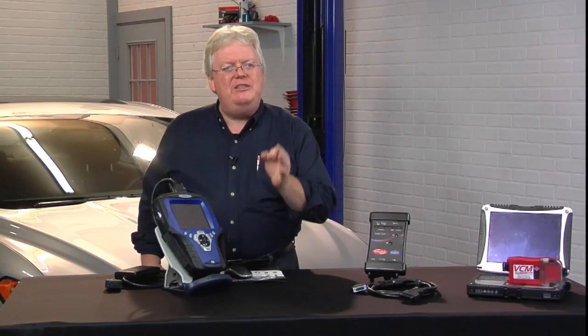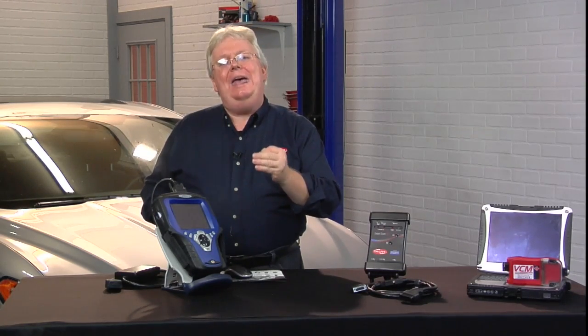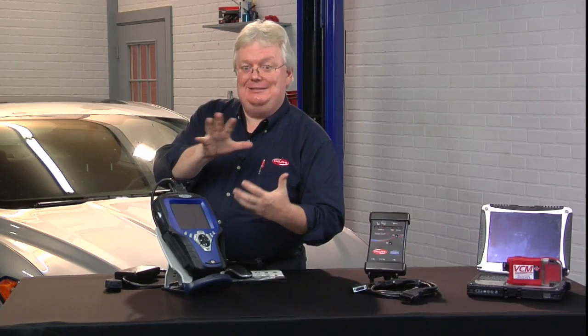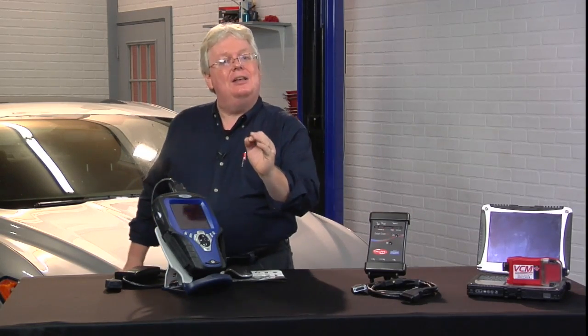Typically, if you see a value that's exactly the same as the specification, it's a bogus value. It's a default because the monitor hasn't been run, or hasn't been run since the last time the code was cleared, or hasn't run fully, whatever. And sometimes, believe it or not, the monitor will say it's run, but it hasn't fully run. You've got to clear the code and try to really run the monitor. Normally, if it says it's run, it's run. If it says it hasn't, it hasn't, but there are exceptions.